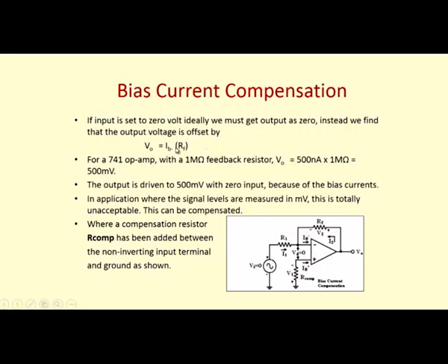So if the input resistance is 10 kilo ohms, then the resistance RF is also higher than the input resistance, because the gain is RF divided by R1 and R1 is the input resistance of the amplifier circuit. So RF cannot be made small, so we cannot go with this as such.